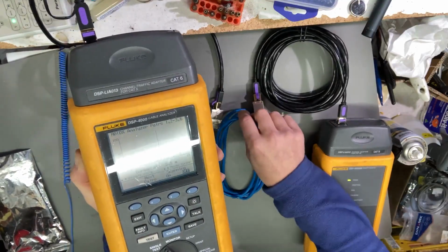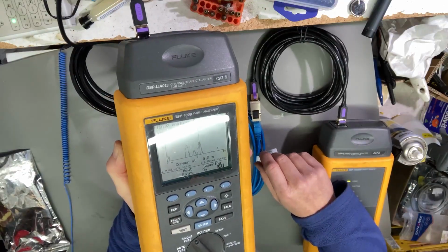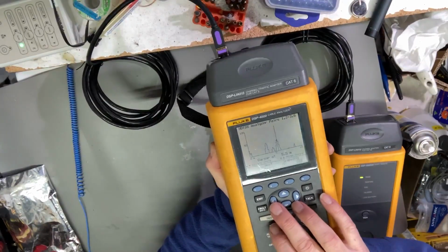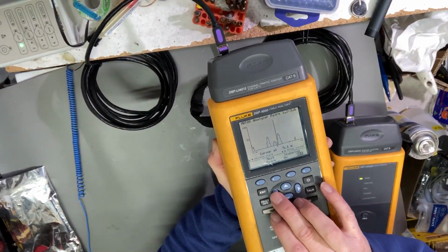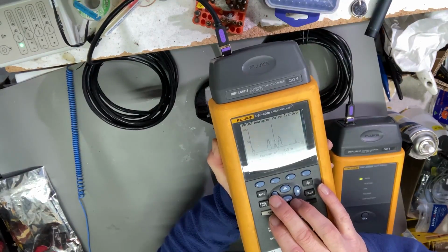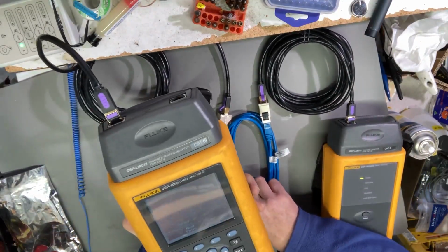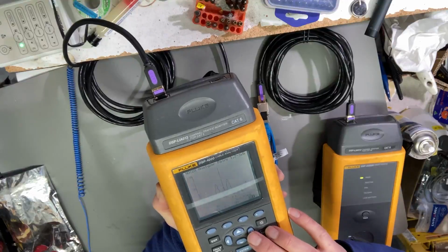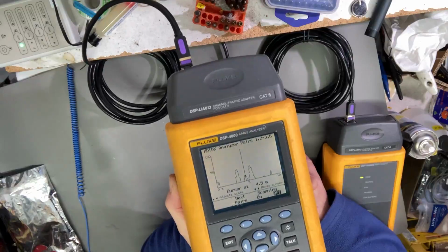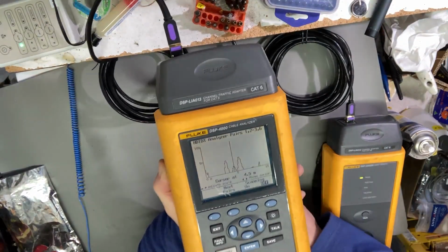So if there was a twist and some damage, and I'm not saying that there's a break in the cable, just maybe it's twisted too tightly, maybe there's some water ingress, you would expect to see some lumpiness where those connectors aren't. And if we have a look in there, right there, see what have we got? 3 plus 3 plus 2, that's 8 meters. So right there in the middle is that highlighted one with the cursor right in the middle between those 2 bumps. That's basically the bad cable.